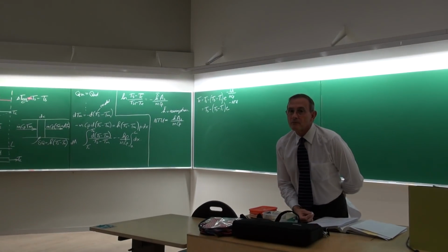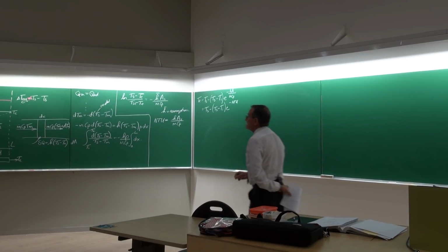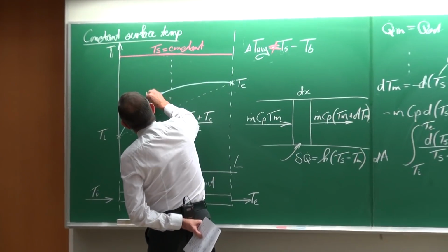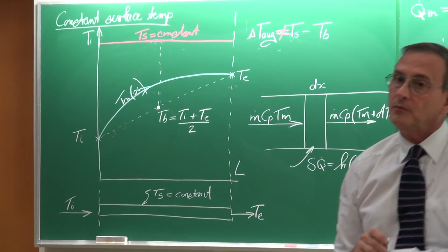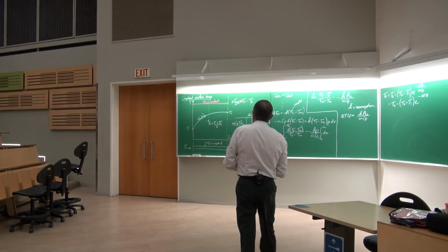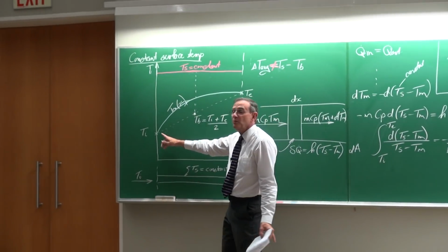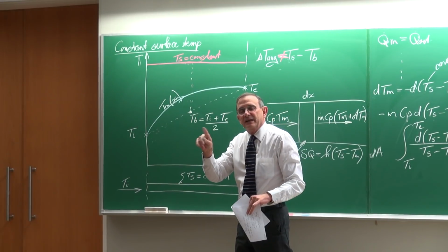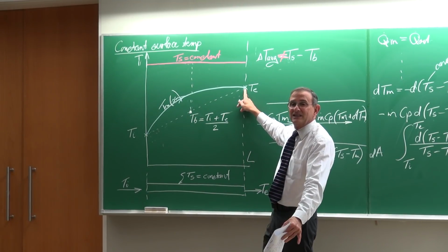In this application, Ts and Tm will not be the same. Correct. Ts is the temperature of the surface. Tm is the temperature of the fluid, which varies right through the channel. The Cp, what would that be of? Cp changes. It's a good question. The Cp will change, and you can go and check water. For example, if you have an inlet temperature of 20 to 60, 4,180, you can see it will change from 4,180 to maybe 4,160.